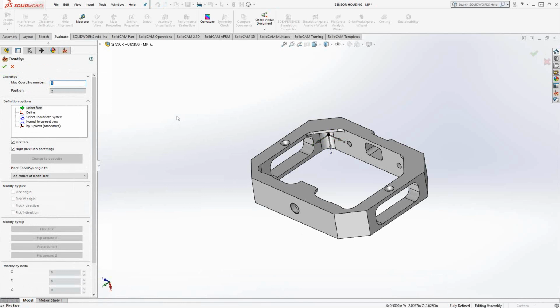So in the same part file, I'm going to program for Mac 2. That'll be my G55, that'll be my E1, my E2, my P2, whatever it is you're looking for. This is the second side of the part. On the machine, I'm taking it out, flipping it around, putting it back in my vise. Inside the software, I'm just giving it a new coordinate system.